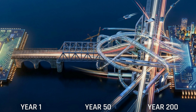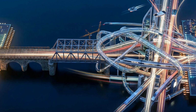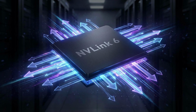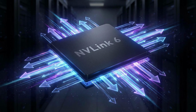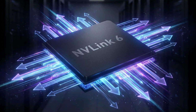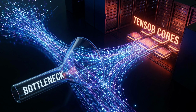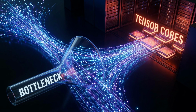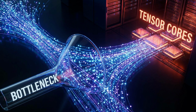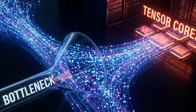The evolution of these interconnects, such as NVIDIA's NVLink, perfectly mirrors the exponential growth of neural networks. While early iterations provided modest uplifts over standard motherboard connections, the modern 6th-generation technology enables an astonishing 3.6 terabytes of bidirectional bandwidth per single processor. This speed is over 14 times the bandwidth of the absolute fastest standard connections available, effectively removing the physical bottleneck and ensuring that data pathways do not starve the computational throughput of the tensor cores.